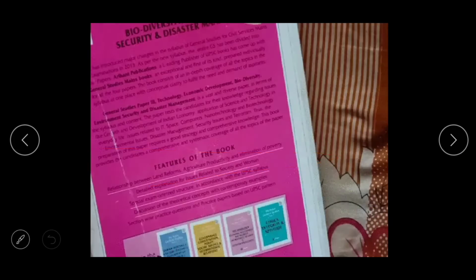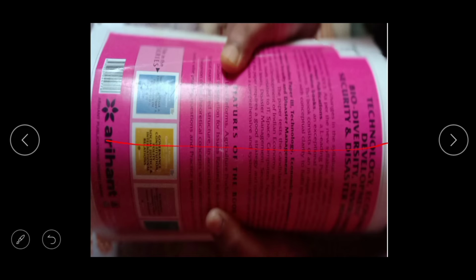See here, suppose a book is there. Here I am trying to bend this book in this direction as well as in this direction, but in this direction it is quite difficult, while in the opposite direction it is quite easy. Here I am applying the bending forces in this direction. So the moment of inertia about this direction is less as compared to this direction.